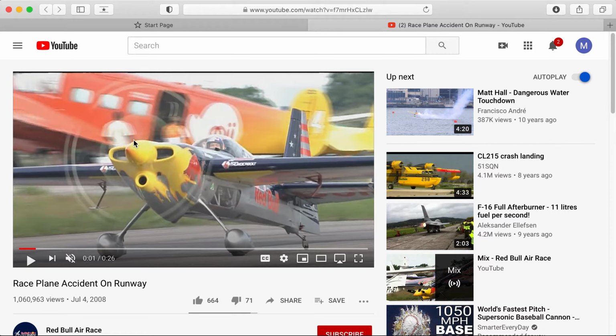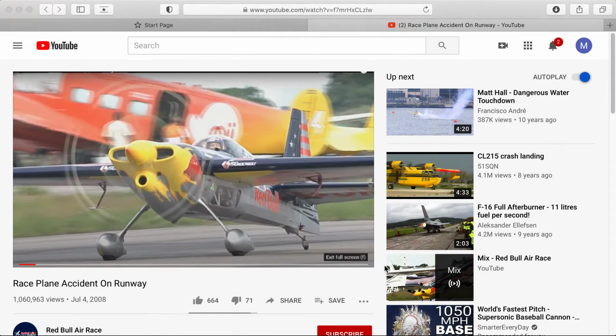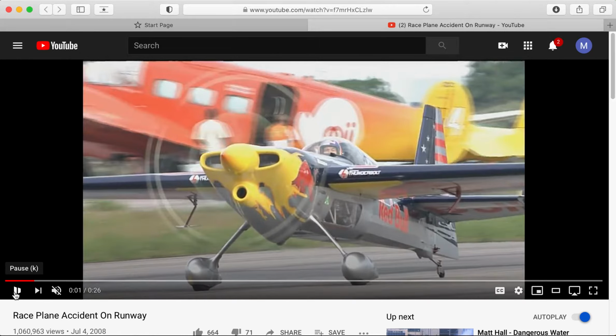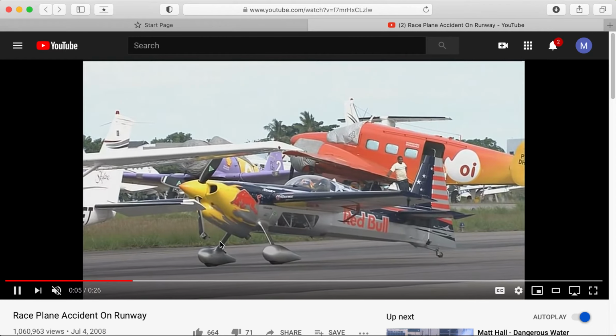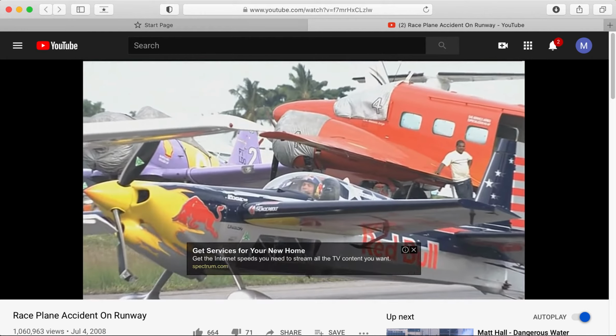There's a few ways around this. You can kind of do S-turns down the taxiway. To exacerbate this problem, to make it worse, he's got a shorter canopy on there to make the aircraft just a little bit faster, so he can only sit up so far. And then let's not do it that way. And let's see what happens. He sees the aircraft too late, slams on the brakes, destroys his own propeller and his own engine to save the airplane who was parked right in front of him.